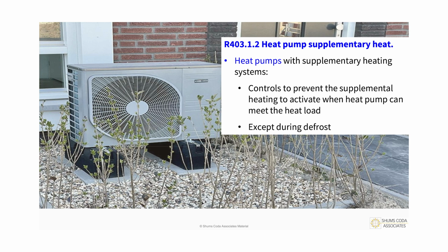If there's a malfunction in the compressor or with the thermostat, the supplemental will kick in. During defrost, it'll kick in. And then if the heat pump is not able to maintain the temperature inside the structure, then it would kick in. But in the 21, there isn't.